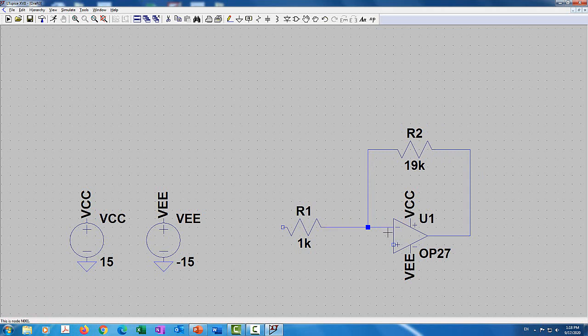so that you don't worry about this leakage current. Now there are some special op-amps with very small input bias currents. But in general, there will be some input bias current going into the op-amp. It's not zero, and that's why you want to make sure that the biggest values of the resistors are moderate. Right? I'm going to ground the other side of R1 here.